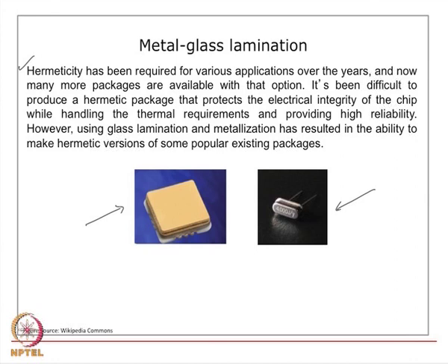Now, another important aspect that I would like to discuss at this point of time is the time for signals to propagate between pins, between devices or between active processors, for example, known as interconnect or RC delay. Most of you are aware of this term, resistance capacitance delay. It is a very important effect that takes a dominant nature when you power up the circuit, and it can eliminate the benefits of higher density, smaller devices.